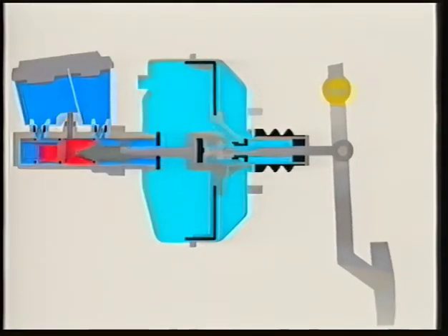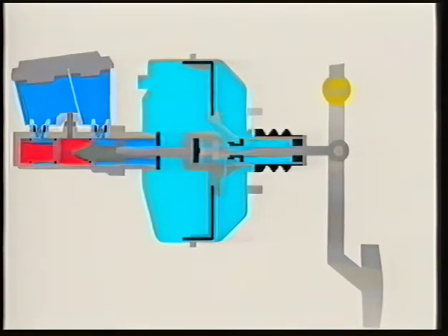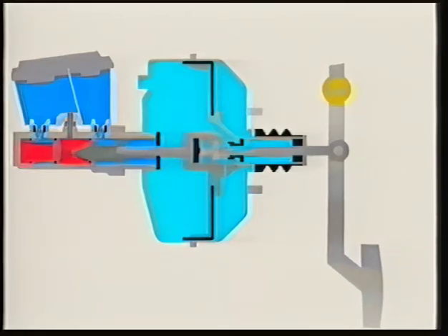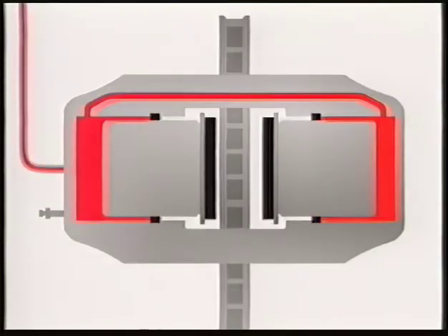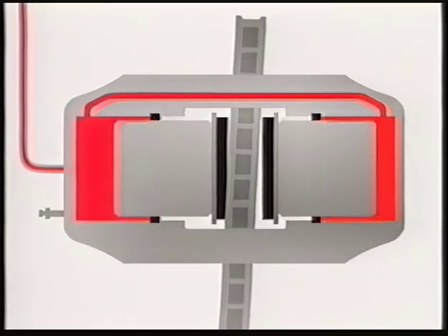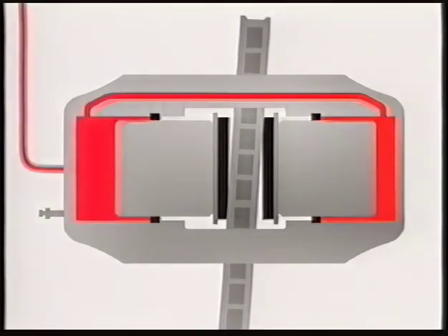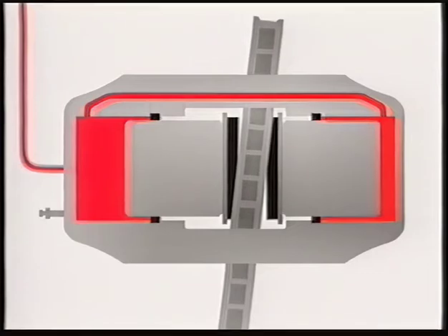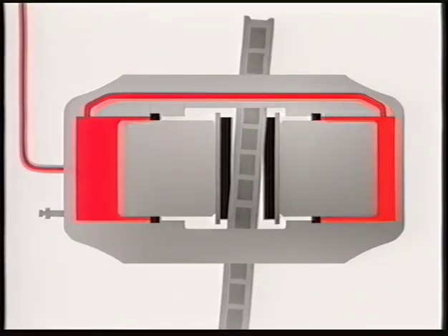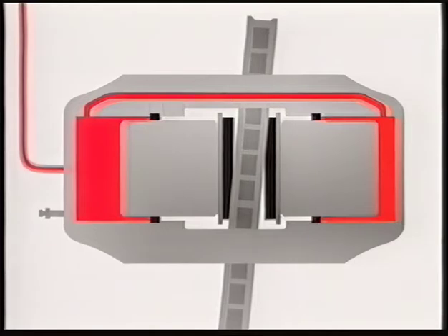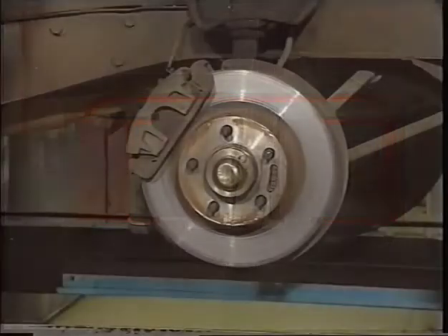This naturally results in increased piston movement, making the master cylinder displace more fluid and leading to an increase in pedal travel. With the fixed head opposed piston caliper, the problem is basically the same, except that in this case it is one of the pistons that does not move instead of the caliper body. The result will, however, be the same, and pedal travel will increase as the pads are worn down.